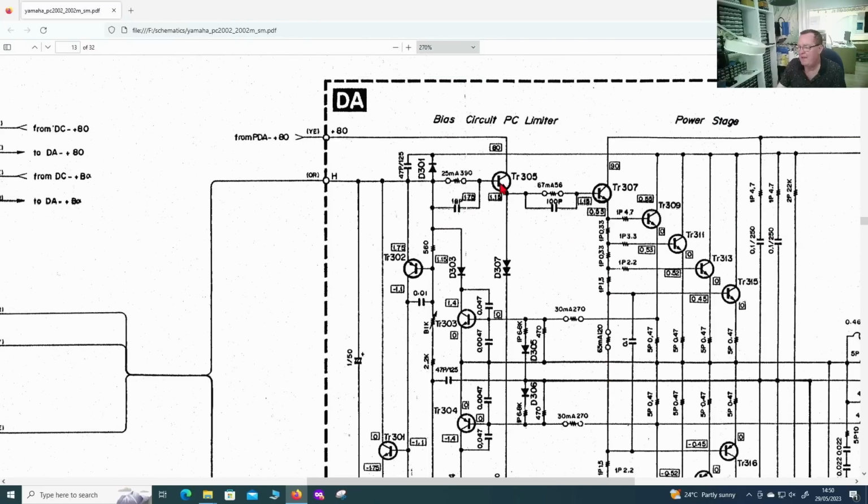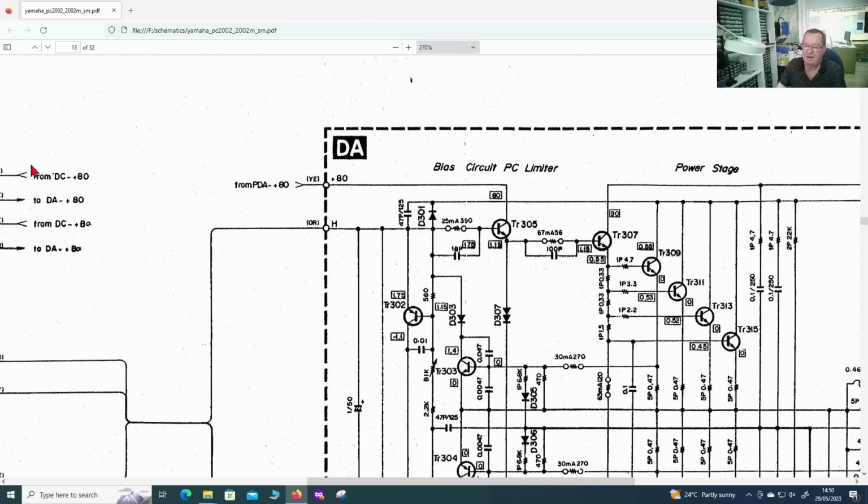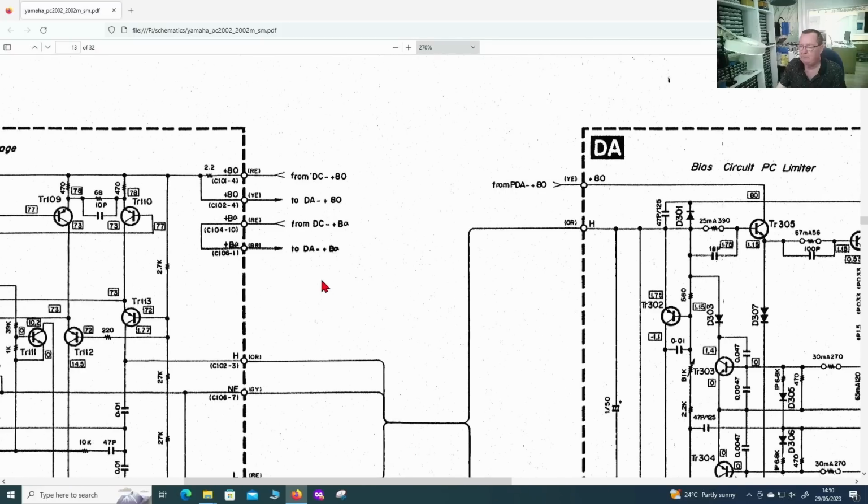So I don't see any obvious path in here to cause a short, or rather 75-80 ohms between there and ground. But we should be able to figure this out by disconnecting this yellow wire if we can. If we disconnect the yellow wire, if the fault is still there, the problem is over here. If the fault isn't there, the problem was over there.